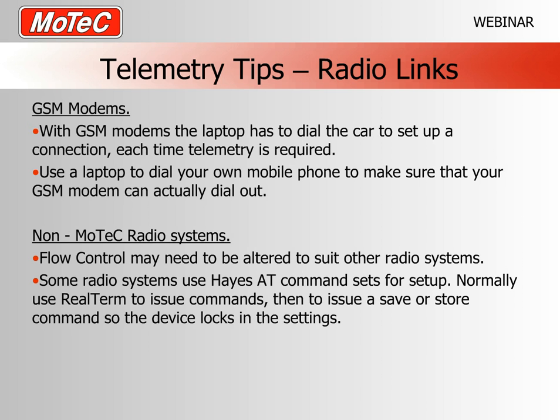Okay, now the last category here would be radio systems that aren't supplied by MoTeC, and in this case it's very difficult for us to give you detailed help. Firstly, it's important that you have your flow control set up correctly. Again, we suggest you start with no flow control, but in the case of some radio systems, if they're not capable of keeping up with the data speed, then they may require flow control.